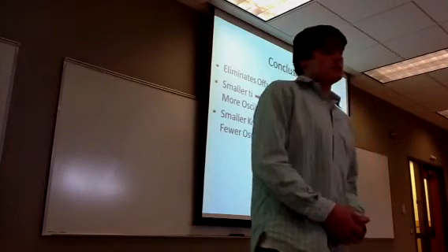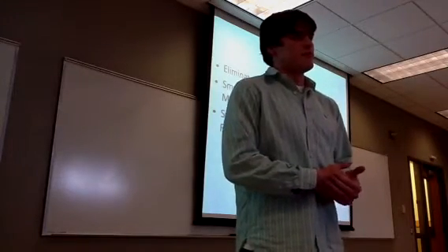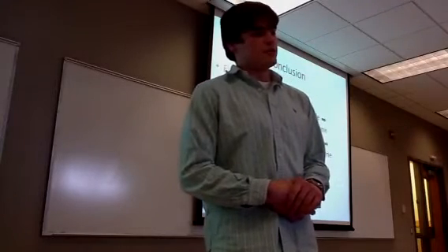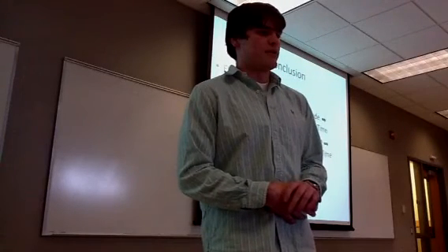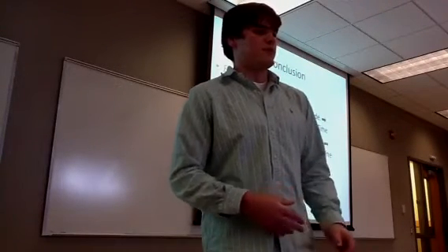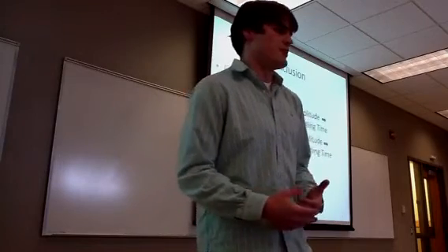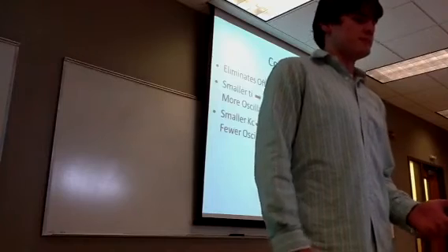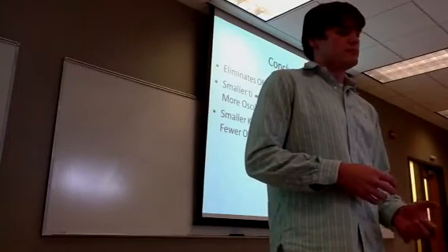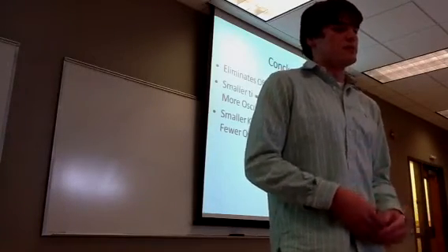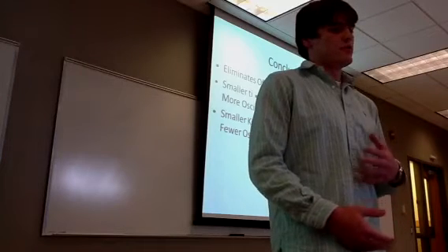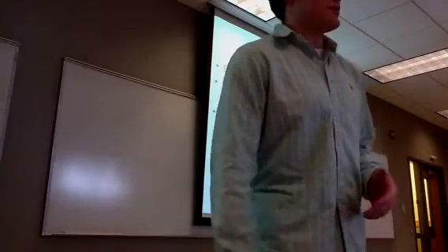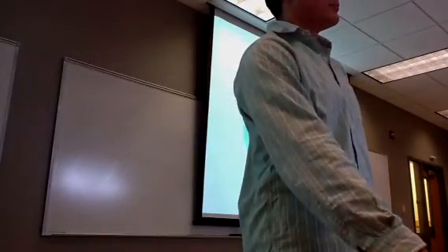In conclusion, the effects of the PI has no offset. The smaller that tau sub I is, the higher the maximum amplitude is, which creates more oscillation and creates a larger settling time, while the smaller the KC does the opposite effect of creating a smaller maximum amplitude, creating fewer oscillations and a smaller settling time.